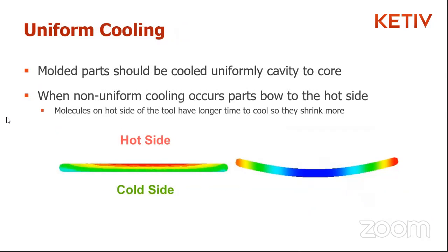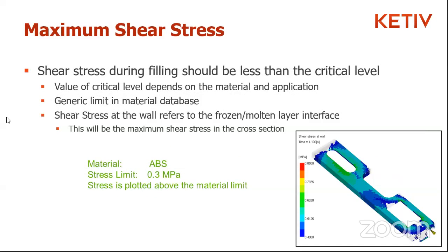Just one comment about that limit. Again, these are guidelines, and this may be a starting point, but say if it's a sensitive cosmetic part, this limit could be a lot higher. Or if it's an easygoing material, say like polypropylene, we know in living hinges, this value is going to far exceed this limit. So again, you're just going to keep the application and material in mind, and what the quality criteria is.